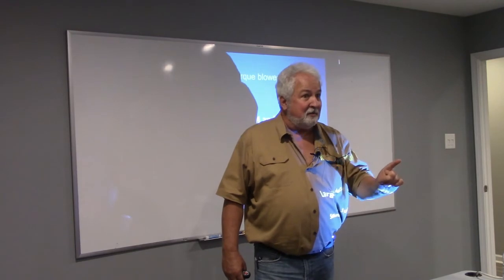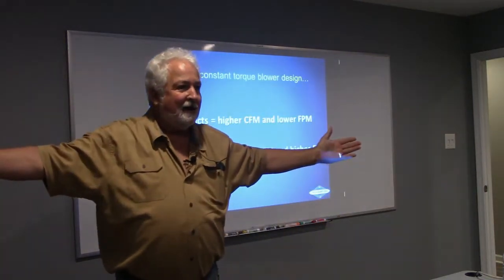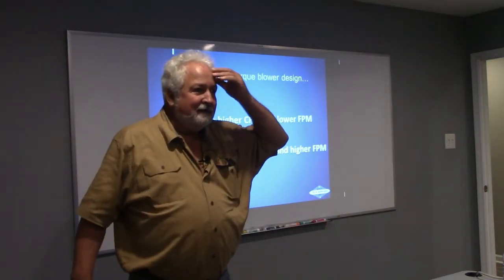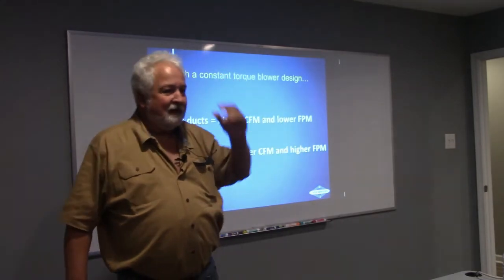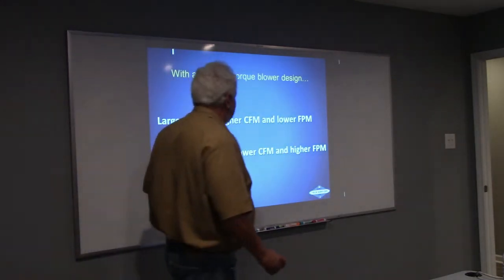It's 98 degree air. It's still 98 degree air. All we did was change the speed at which that air was coming out, didn't we? So those people that are having their heat pump blowing cold air, it's not blowing cold air, it's blowing 98-degree air, but it's moving too fast. Too fast! How cool is that? You following? Absolutely. Cool.